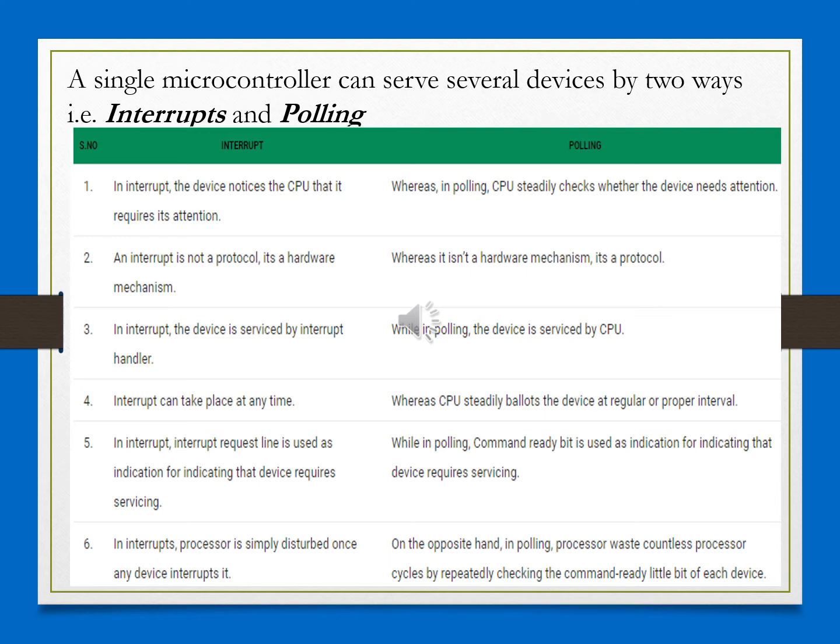Till the overflow flag was set, the CPU was not performing anything but waiting. Only after it was set, the next instruction would get executed. Remember? So there, the CPU is tied up. It is not doing anything, it is engaged, waiting for the overflow flag to get set.